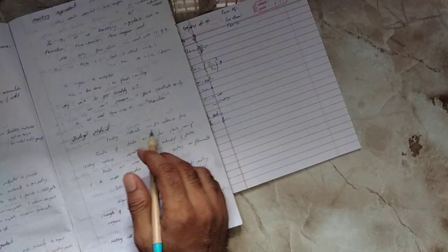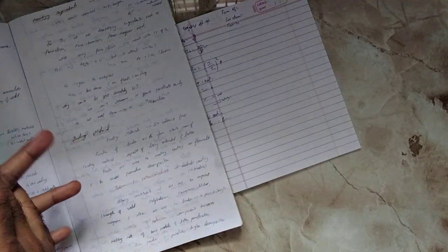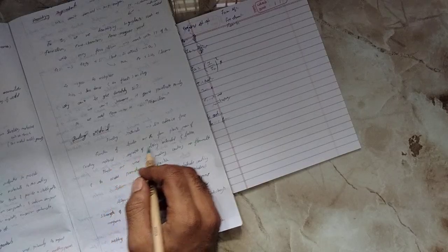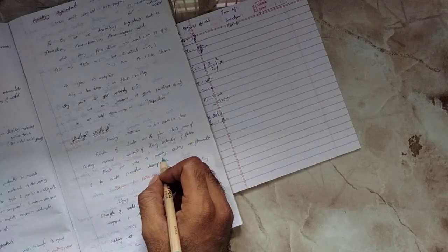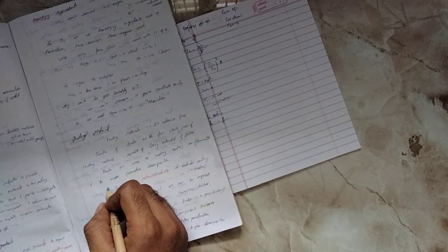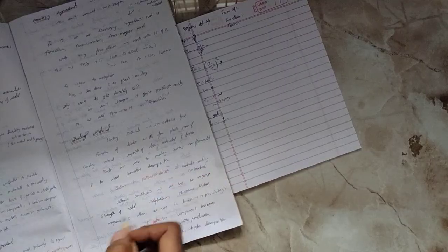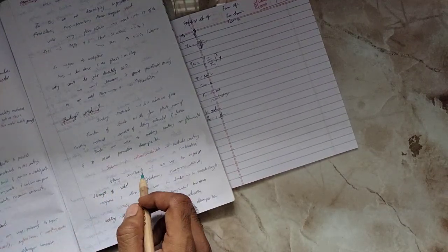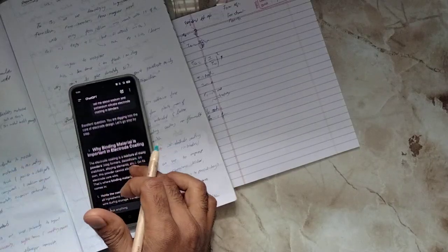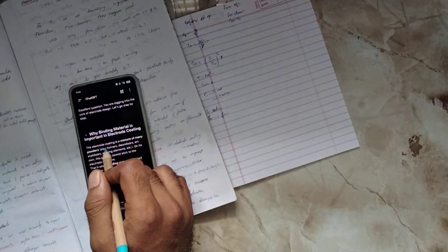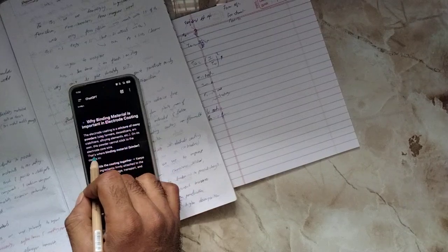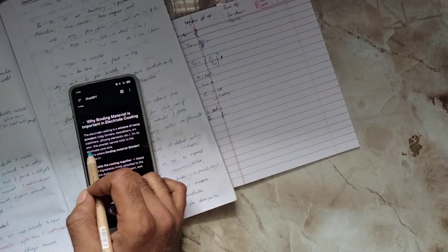Binding material is used to join two kinds of forces. The function of a binder is to form a plastic mass of the coating material, capable of being extruded and baked. Binders are used to make the coating non-flammable and to avoid premature decomposition. Why binding material? The coating electrode has many powders, slag and everything. This powder can't stick to the electrode wire by itself.